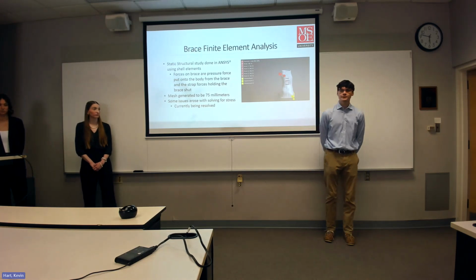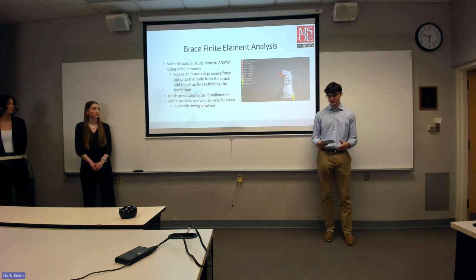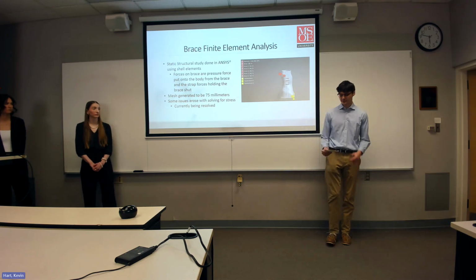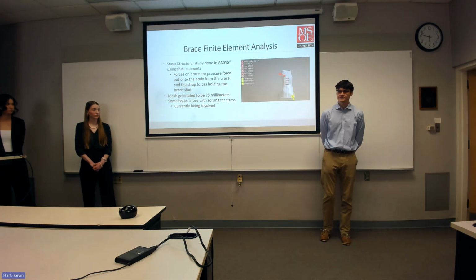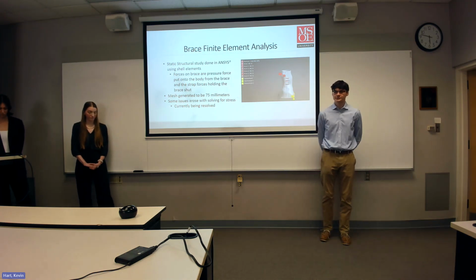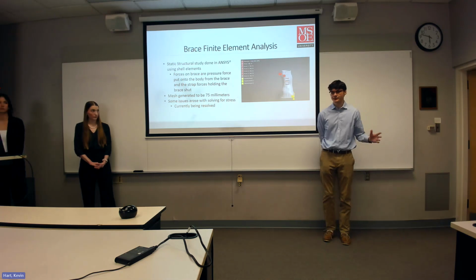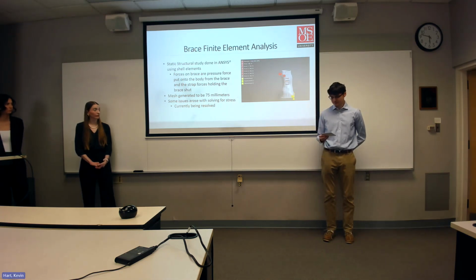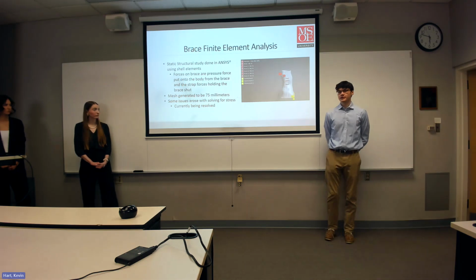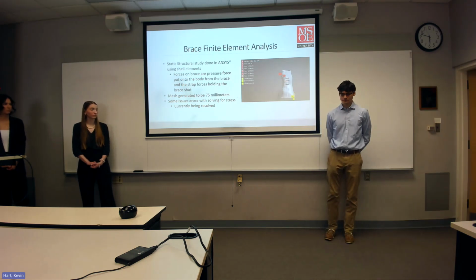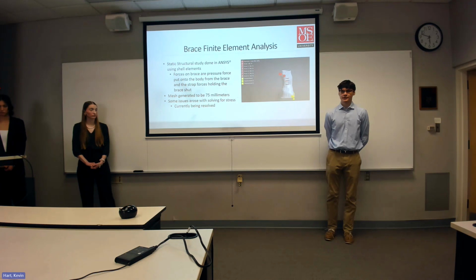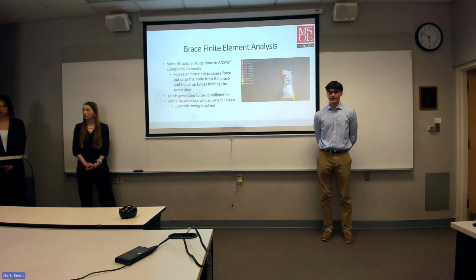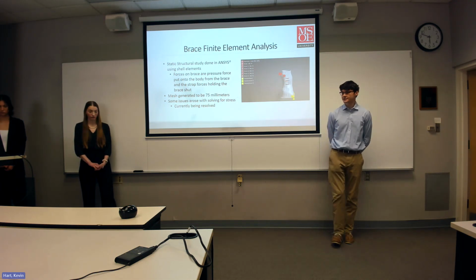So to analyze the material properties of the brace under load, a static structural study was done in ANSYS. Specifically, we used shell elements just due to the shape of the brace, because it's so much thinner than it is tall and wide, so we can estimate that it is 2D. The model was constructed from a 3D scan of the patient, and points were generated, and curves were created from those points. Those curves were lofted together to create the brace, and then a STEP file was constructed and put into ANSYS.